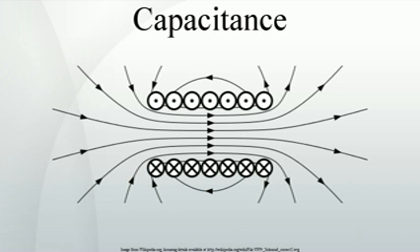Using this measurement method, the dielectric constant may exhibit a resonance at certain frequencies corresponding to characteristic response frequencies, excitation energies, of contributors to the dielectric constant. These resonances are the basis for a number of experimental techniques for detecting defects. The conductance method measures absorption as a function of frequency. Alternatively, the time response of the capacitance can be used directly, as in deep-level transient spectroscopy.